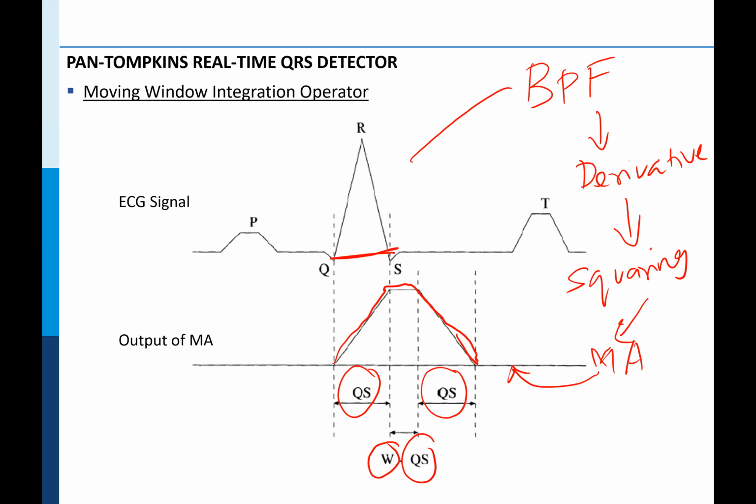That's important because in a lot of clinical contexts, the duration of the QRS complex plays a significant role in understanding what's happening during arrhythmia, in cases of premature ventricular contraction, and in a lot of disorders. So in addition to detecting the QRS pulse, knowing the width is essential, and that's exactly what the output of the moving average filter allows us to do.